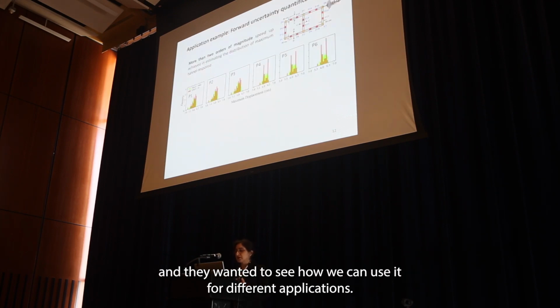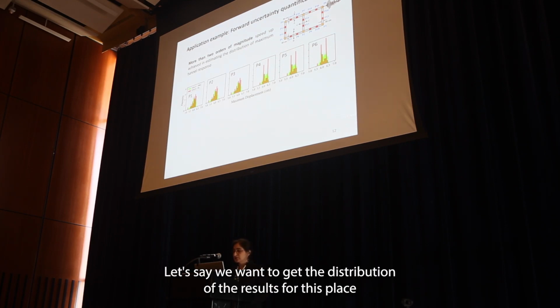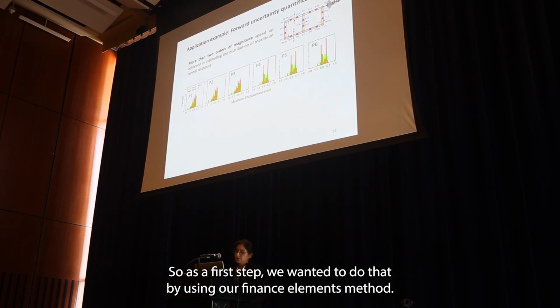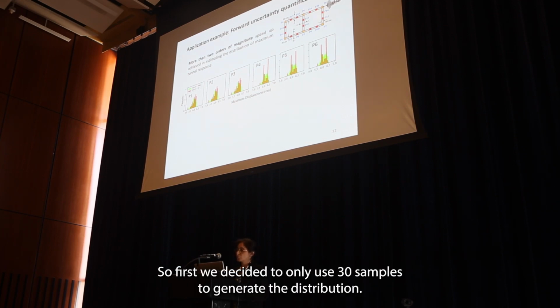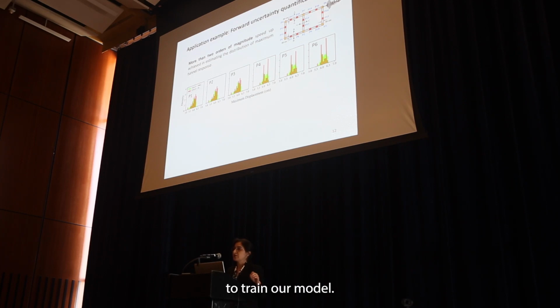And then we wanted to see how we can use it for different applications. So the first application is forward uncertainty quantification. Let's say we want to get the distribution of the maximum horizontal displacement at different locations from P1 to P6. As a first step, we wanted to do that by using our finite element method. So first we decided to only use 30 samples to generate the distribution, and the reason for choosing 30 was because we used the same number to train our model.